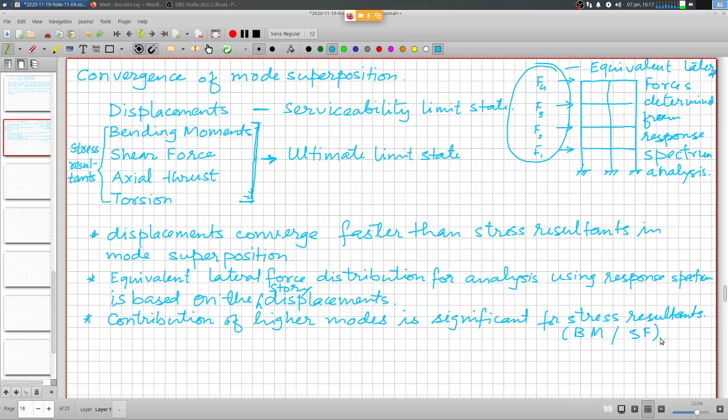Columns in several upper floor stories of well-designed buildings got damaged during that earthquake. Upper floor damage is very unusual, because the building is like a tall, almost vertical cantilever system. As you go on adding up the shear force, it actually increases towards the bottom, shear force and bending moment. So why should the failure happen at the top floors?